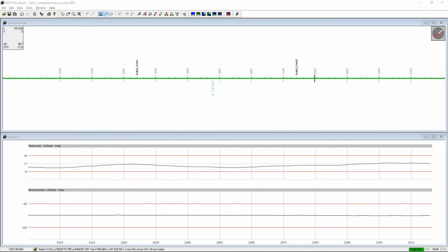I'm going to divide this straight element by inserting two constraint points and basically locking the straight element between those 2 points. So the shift and lift values at these points will be equal to 0.